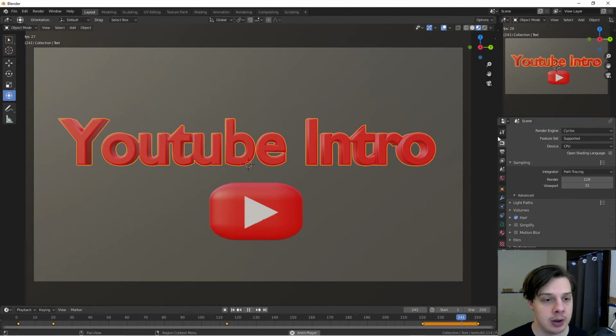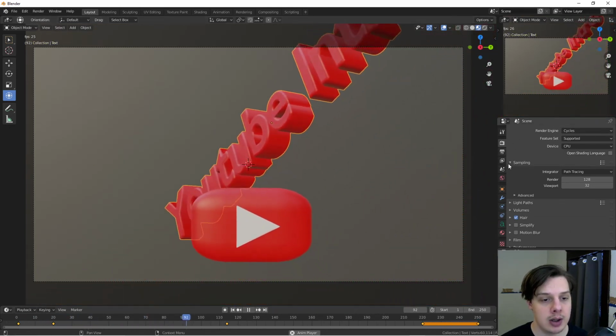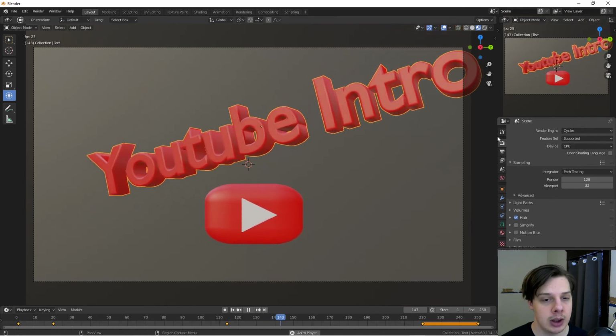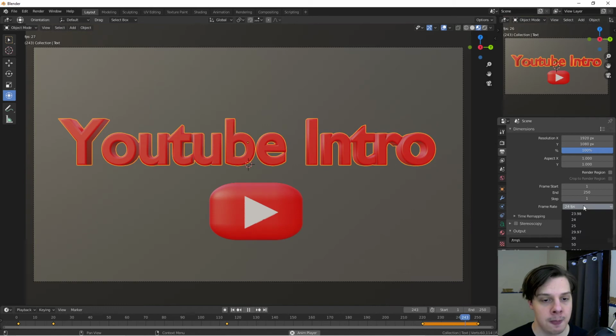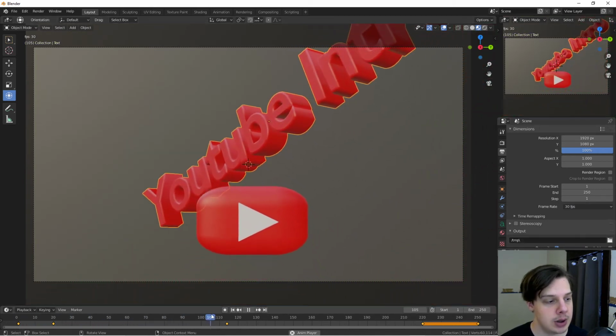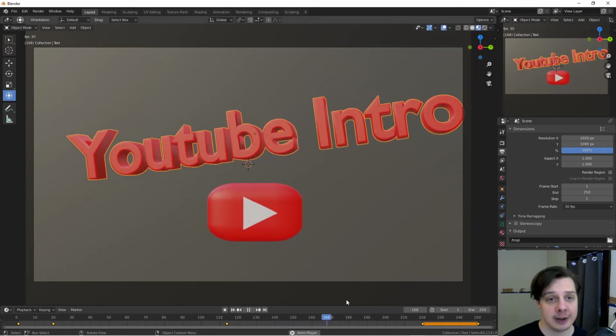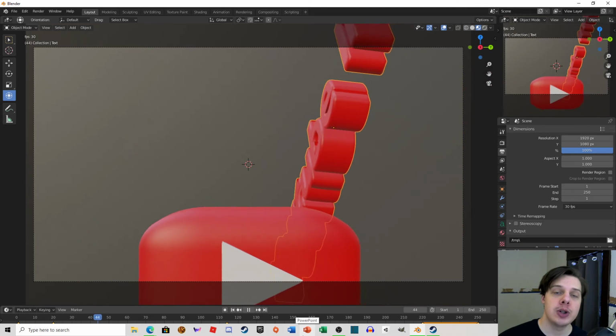To do that, you can click up here somewhere. You click in this panel. You would click this button right here that looks like sort of like a printer. And then where it says frame rate, go to 30. And as you can see, it runs a lot faster now. Although the overall time of the animation is slower.